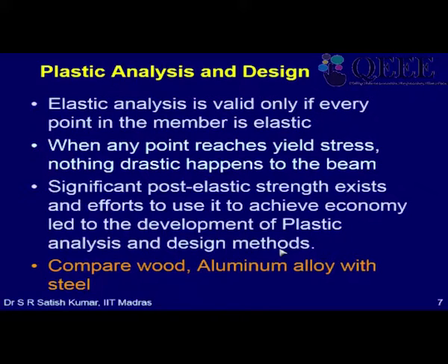It has nothing to do with whether your design is working stress method or limit state method. Basically, it's just an analysis and design method that we are following. In either method, whether you use WSM or LSM, you need to ensure that the deflections etc. are within serviceable limits under working loads, and at ultimate loads the collapse is prevented. When you use plastic analysis and show that collapse can be prevented, you will get a major economy. Okay, so that is the advantage.